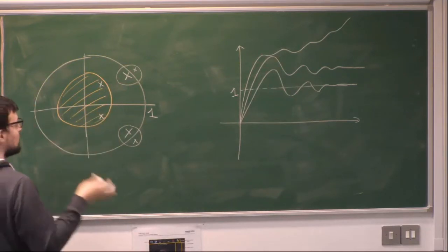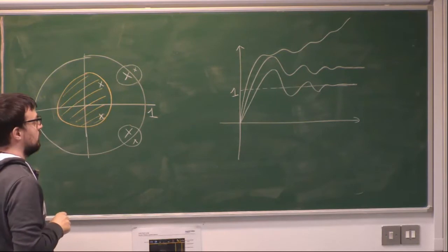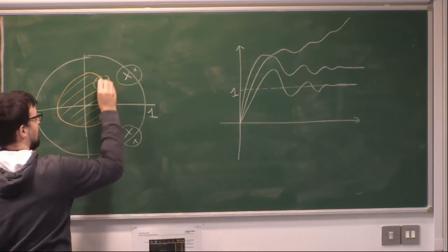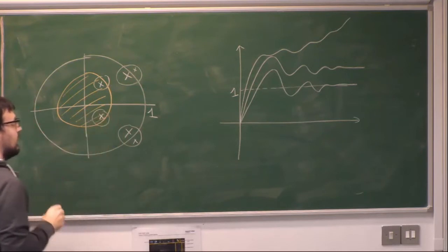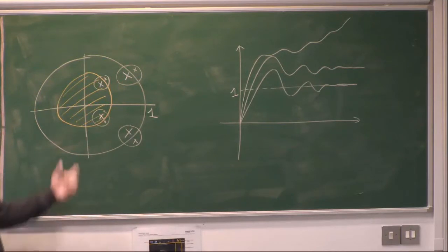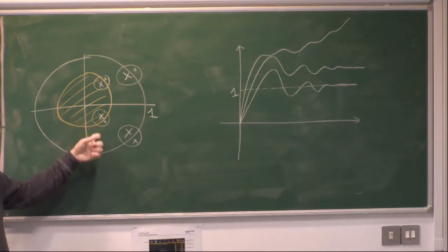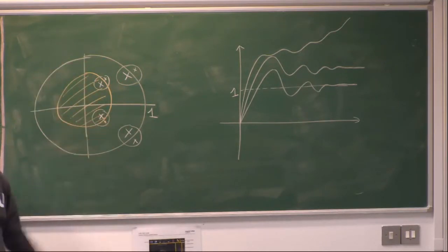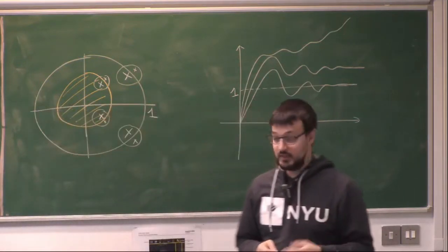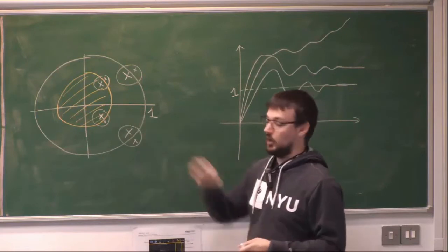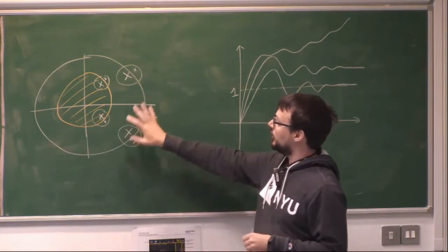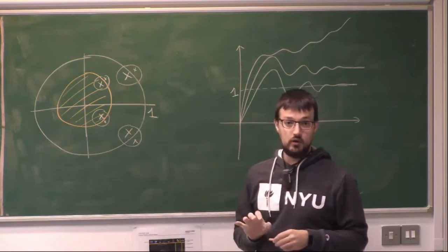Now, again, it's true that our model is not a perfect representation of the physical system, and so it may happen that the poles actually happen to be outside this small circle. However, since we have this margin, the overall system is still asymptotically stable. So this is the basic idea behind robust stability, and this is one type of stability margin, a type of stability margin that is visible on the root locus of the system.